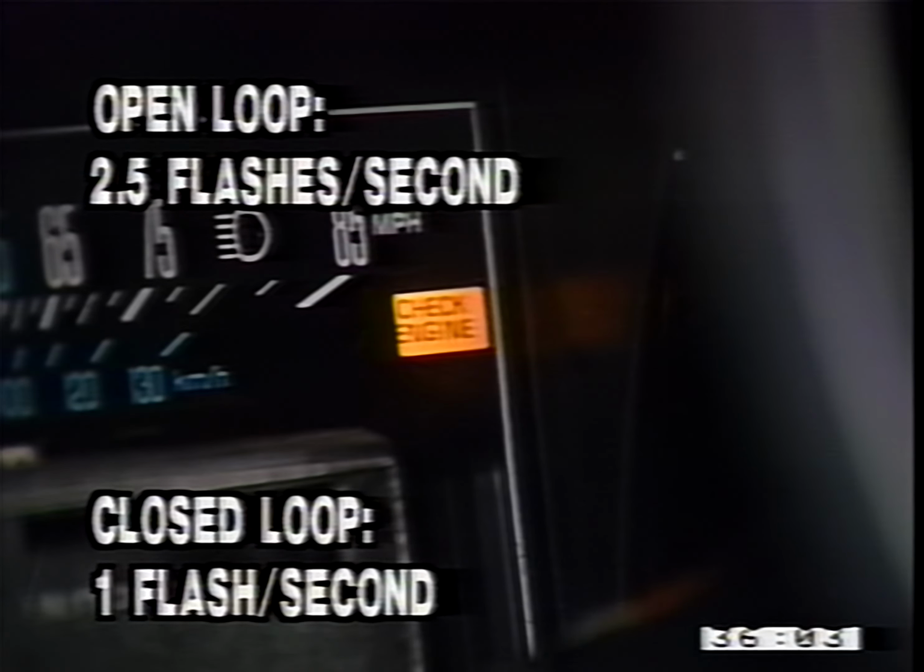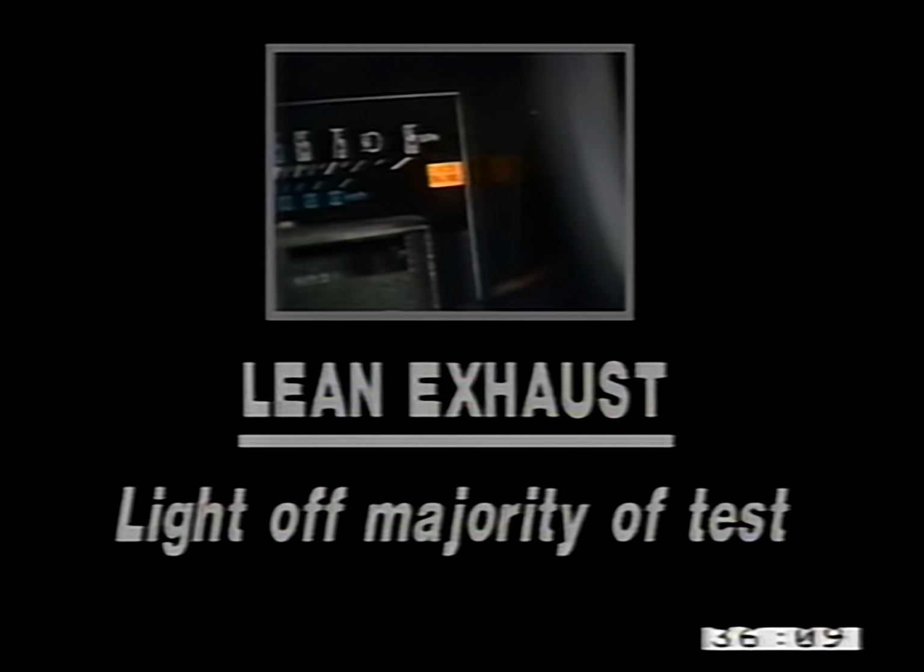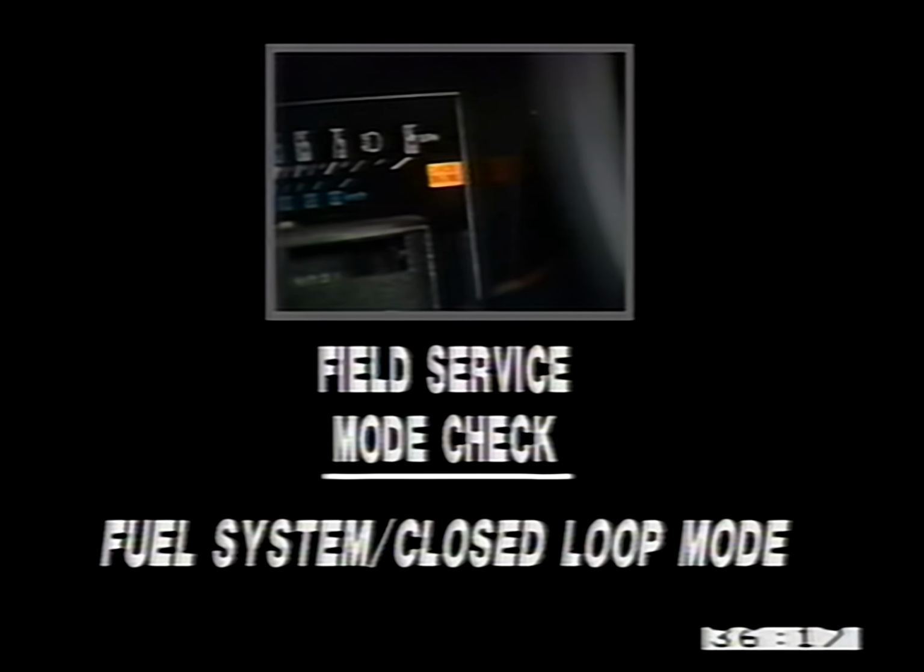The light will flash at 2.5 flashes per second to indicate proper open-loop mode. The closed-loop mode will be indicated if the service engine warning light flashes at a rate of 1 per second. A lean exhaust is indicated if the light is off most of the time during this sequence, and rich if it is on for the majority of the time. The field service mode check for fuel-injected vehicles confirms that the fuel system and closed-loop mode is operating properly.